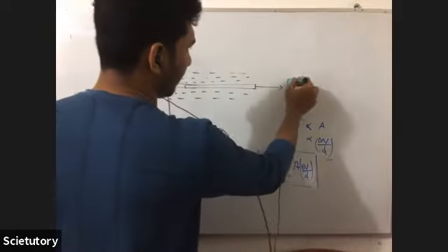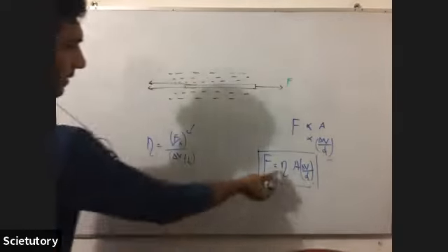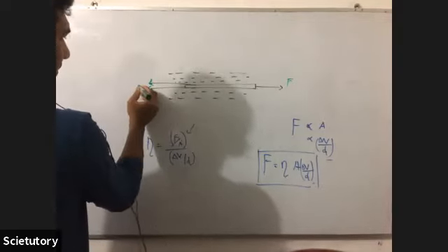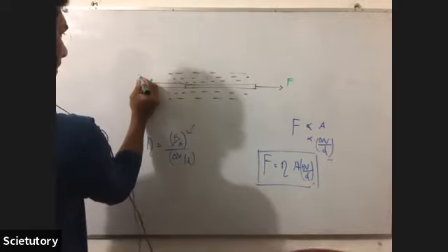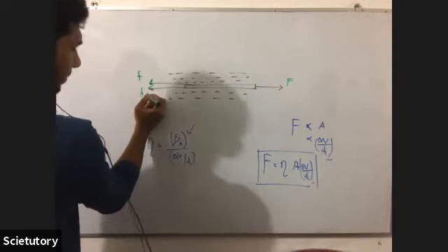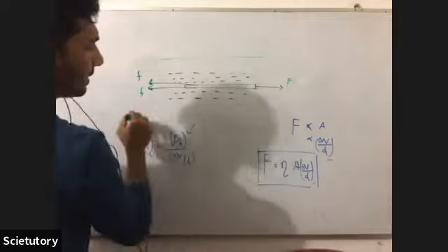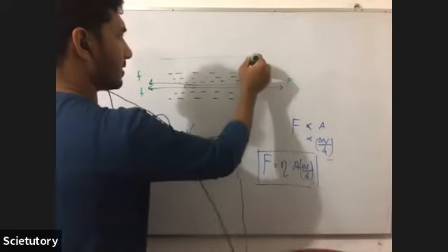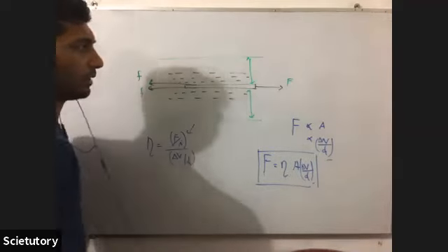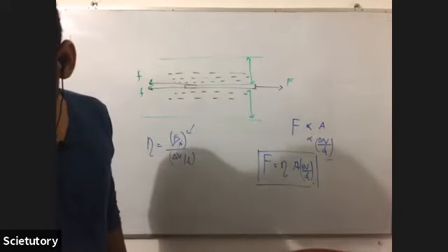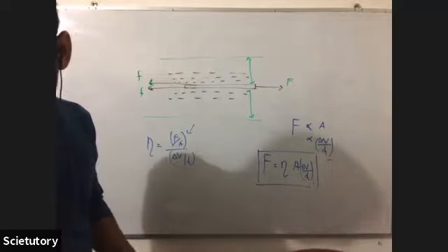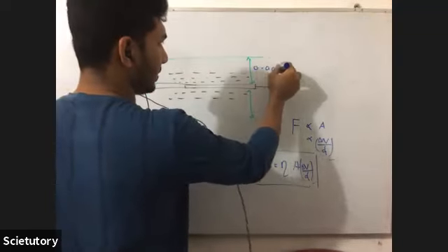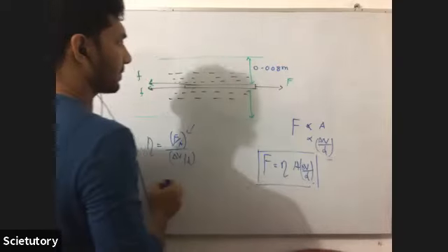So when you give F, according to this equation, there is a viscous force like this and this. So there are two viscous forces, no? One is small f, the other one is also small f, because it is traveling in the median plane. Okay, so now the distances below and above the plate are equal. The total is 0.016, so one is 0.008 meters.